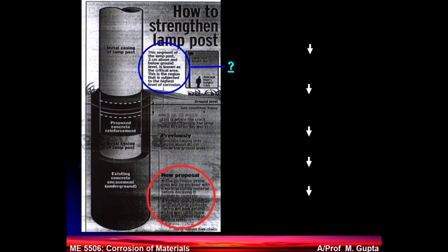Because it's a damp area, your water level is there. A typical humidity level or presence of water is there. The only difference can be the difference in the oxygen at the surface and below the surface. And when you go to waterline corrosion, again remember the corrosion takes place just about an inch below the waterline. So that is how much difference an inch, which is 2.54 centimeters to be exact, can make.